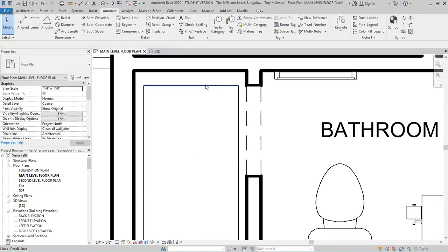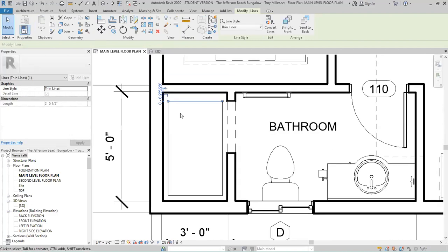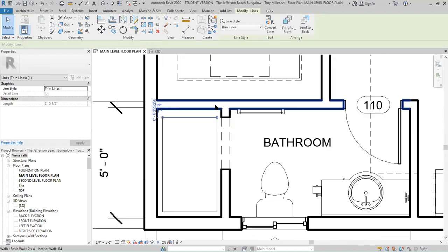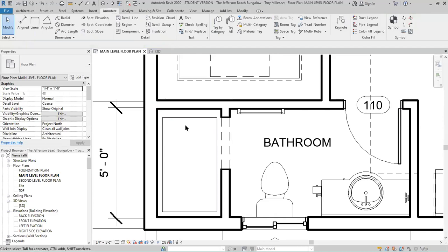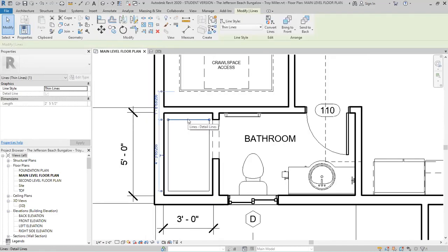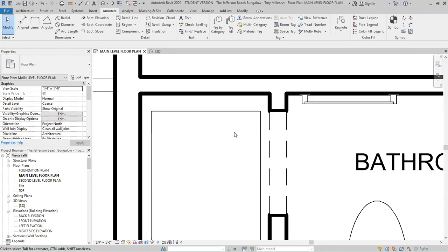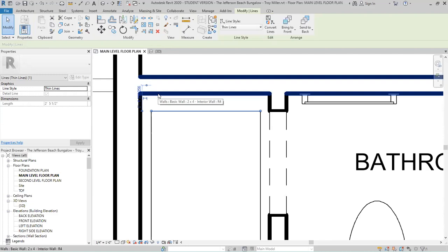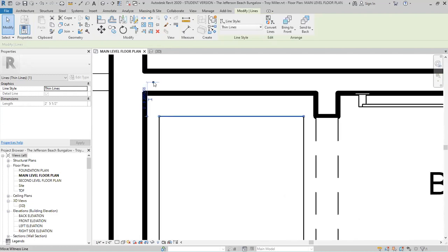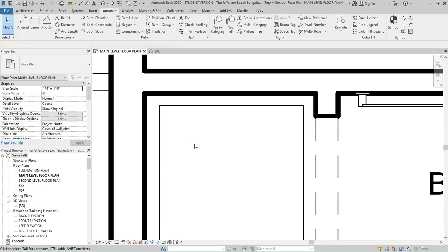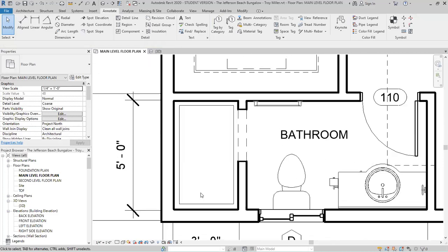Okay. And once again, if I snap to here, you'll see, oh, that's interesting. This time it actually did snap there. So let me, I'm curious here for a second. Okay, so when I'm zoomed out, it's snapping all the way to there. If I zoom in to where those symbolic lines on the other side do not appear, it looks like I snapped there. So I actually was not aware of that until just now. So now I'm going to go ahead and snap that line into place, click there, and that's going to prevent me from having to put a bunch of temporary dimensions in.